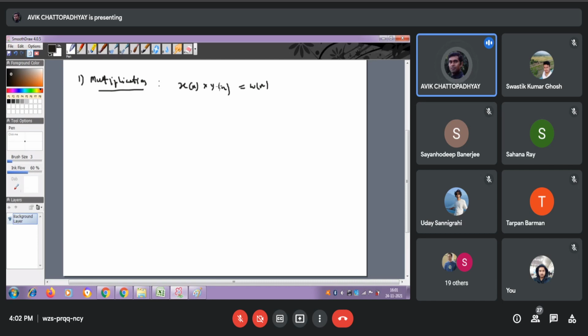A very popular question people ask: what do you mean by zero adding or padding? The length of the signal should be the same while multiplying the corresponding samples, so that there is no ambiguity or confusion. Wherever there is no sample, you just plug in a 0 value.